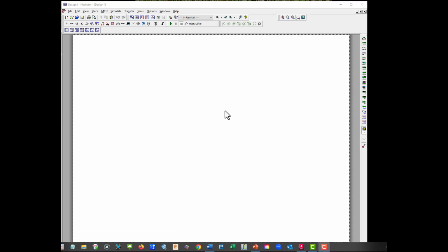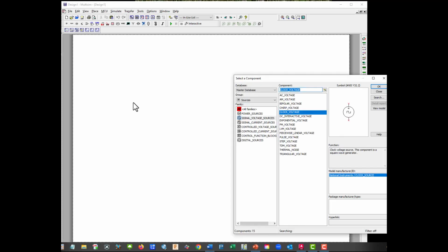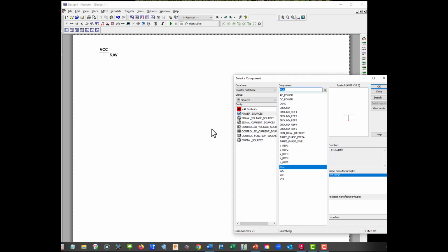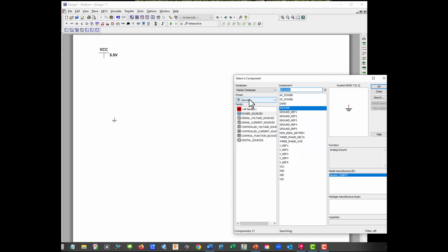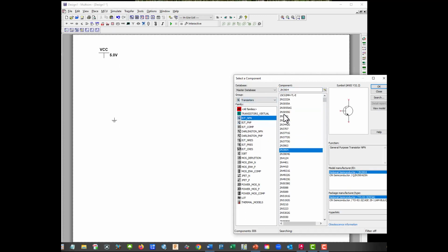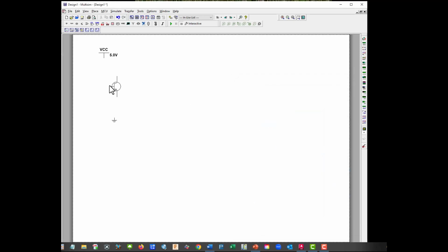Okay, let's build our voltage divider circuit for NPN. Let's grab some grounds. Let's grab a VCC. Let's grab a ground. We need a 3904, sorry. Transistor, NPN, 3904.